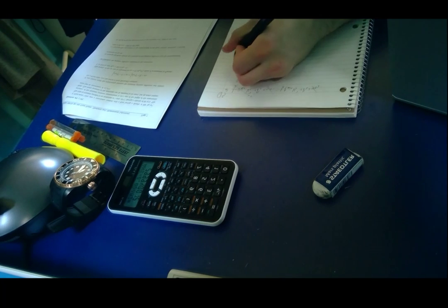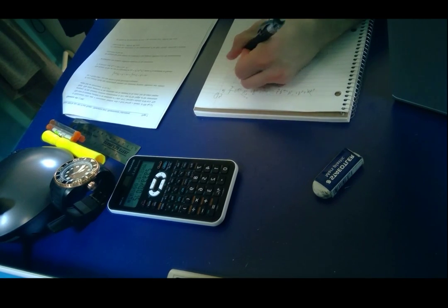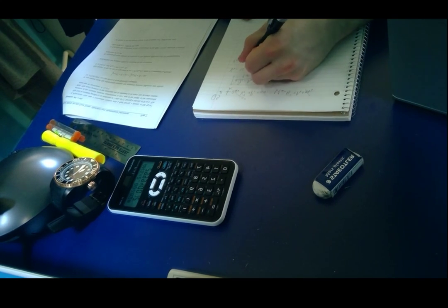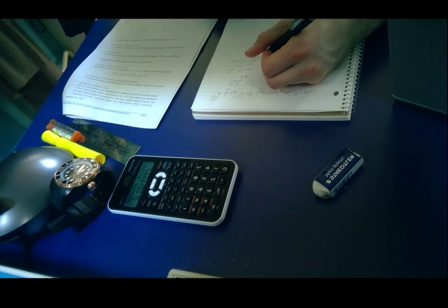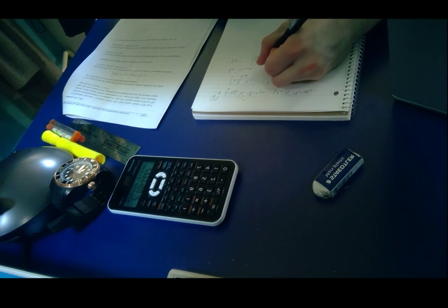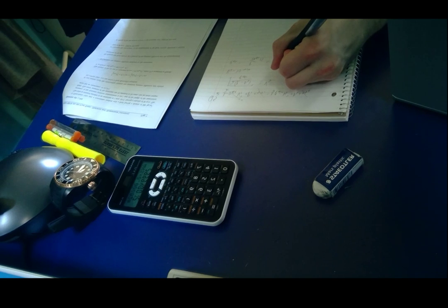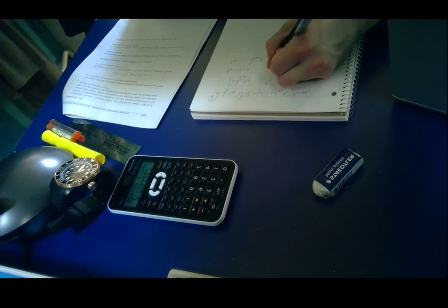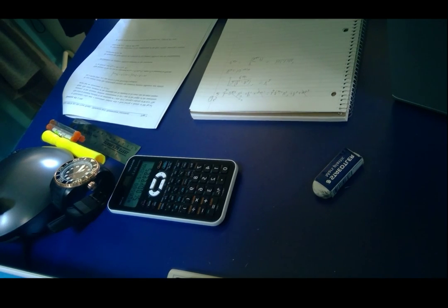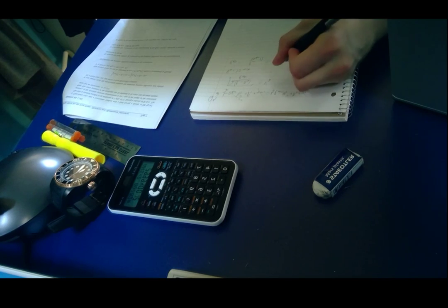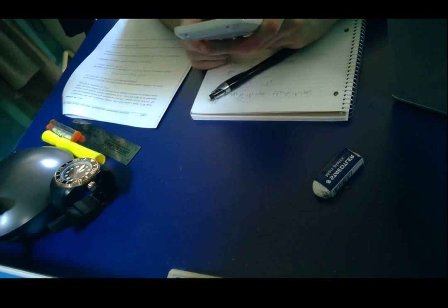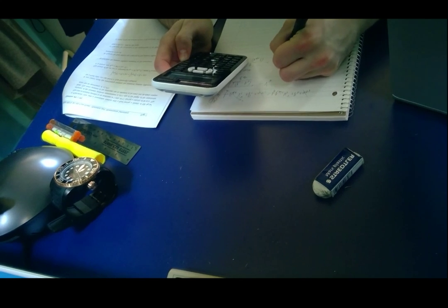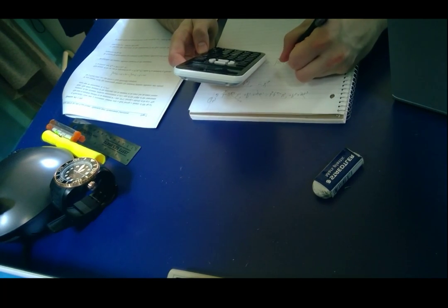And that's nice. Now the rule of air, we actually have an equation for it given to us by our Lord and Savior Milarski, which is P, pressure, divided by the R of air, constant given to us by Milarski again, and T, where T is in Kelvin. Never forget it. So that is pressure of 101.3 times 10 to the 3 pascals, because it's 101.3 kilopascals, atmospheric pressure, and that's our initial variable. The temperature will be 273.15 plus 25, so 298.15, times the R of air, which is 287.